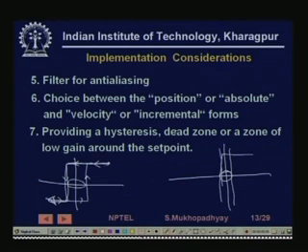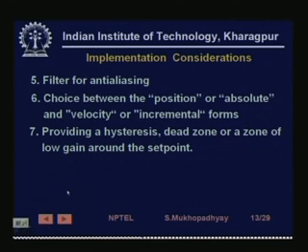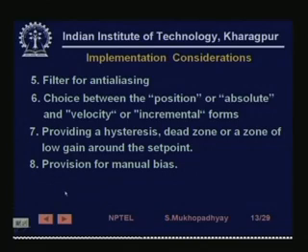Now, you can have a smooth hysteresis comparator, something like this also. So, you say that I am going to keep the gain and then slowly change the gain. So, in this zone the output is not switched. These things can be done to avoid noise, of course, because maybe you can actually tolerate that much error, and otherwise the actuator will unnecessarily be moving all the time because of noise. So, for some actuators this may not be good.